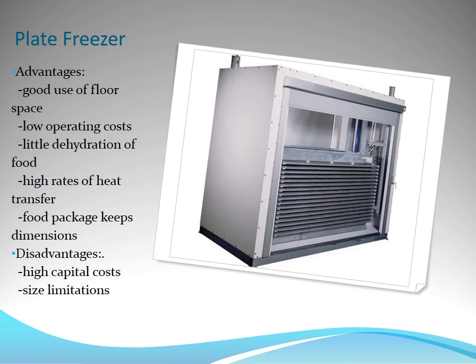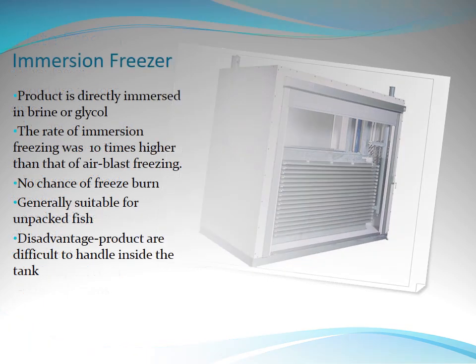Advantages of this type of freezer are good use of floor space, low operating cost, little dehydration of food, high rates of heat transfer, and food packages keep their dimensions. Disadvantages are high capital cost and size limitations.